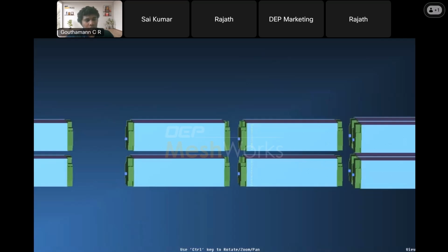It supports both LS-DYNA as well as Nastran. Here I'm going to select a bunch of elements which represents one module. And then I'm going to choose what type of connection it needs to be. Here I'm going to choose that once converting into a mass inertia representation, go ahead and connect them through rigids by using the mounting locations. And I don't have a specific node, automatically the tool is going to find that out. And then I'm going to specify what the connection type is. Either it can be a nodal rigid constraint or constraint interpolation type.